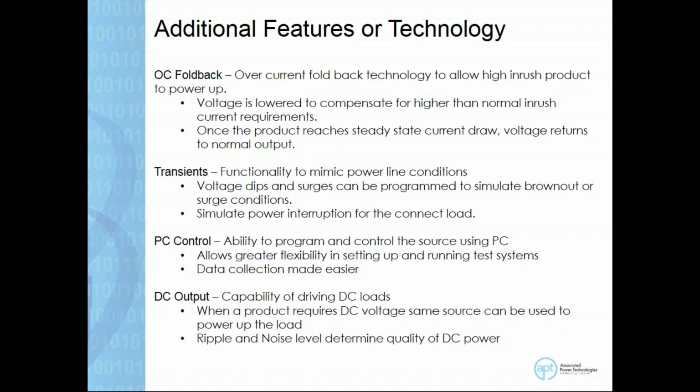When the motors first start spinning, there is a requirement for much more power draw, or much more current is being drawn, but once the motor is already spinning, it may not require the same amount of current. This is what we call an inrush period requirement, having a lot more current for the product, and then a steady state